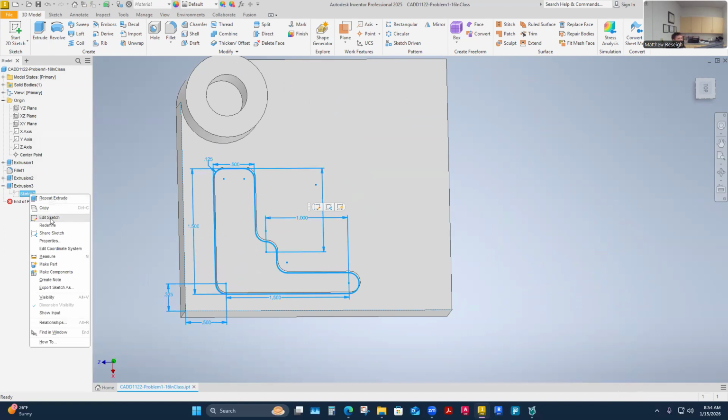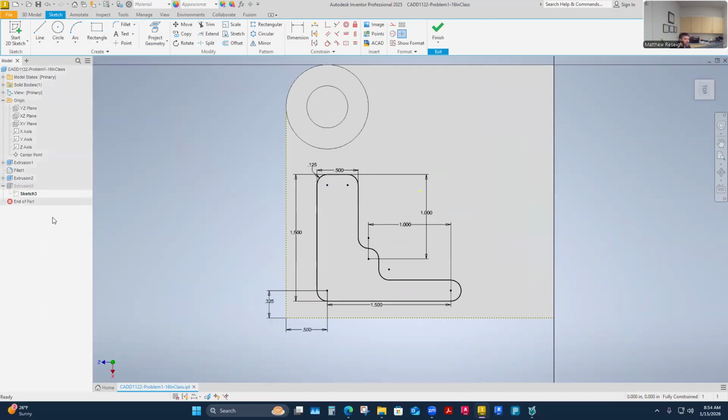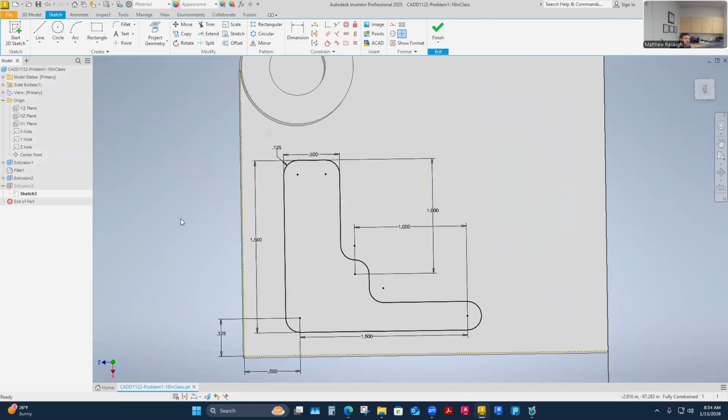Yes, correct. If it's purple, it means it's still not constrained. I usually delete them and then draw a new line. If I find a segment where the way you sketched it makes the geometry start squishing together and you have excessive line segments, I will tend to delete them and then draw in a new line, maybe one continuous line. I don't know if that helps. Yeah, don't be afraid to delete. Even here, I may have had to delete something in between. And when I worked with a few other people who were sketching this, we had to delete some stuff.